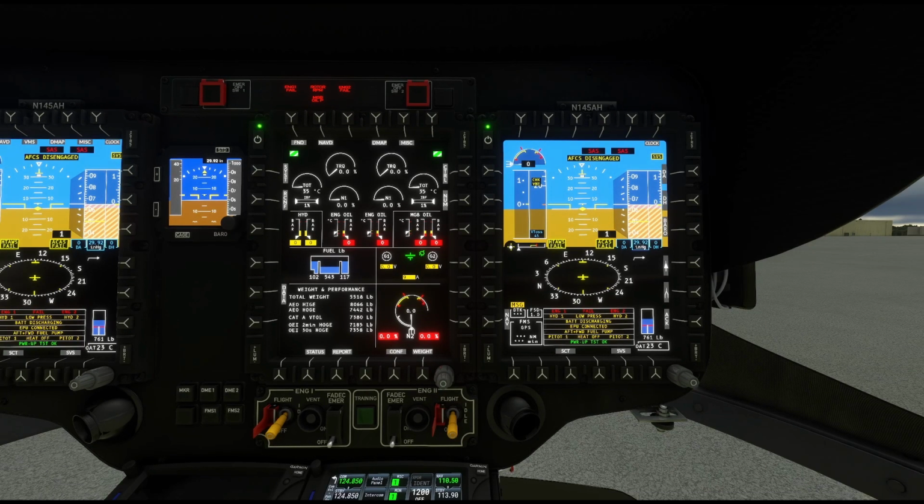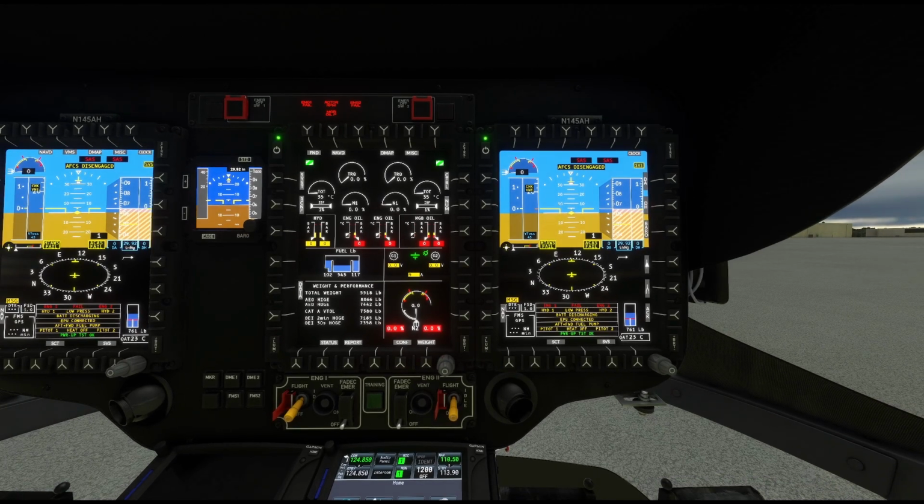So the flight navigation display format, which is what is shown right here, displays your primary information. I am going to go left to right, top to bottom on this. We're going to start out right up here with the triple tach. All right, so the triple tach consists of 3 individual tachometers, okay? So we have our NR, our nominal rotor speed, which is actually this pointer right here. That is backed up by this digital number right here, which gives us a percentage of nominal rotor. 100% is 383 revolutions per minute of the main rotor system.